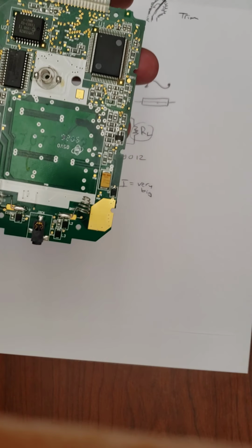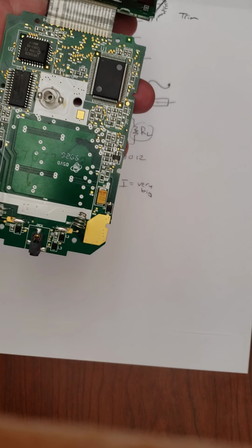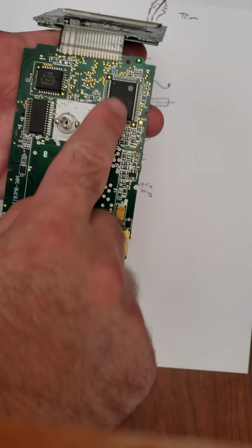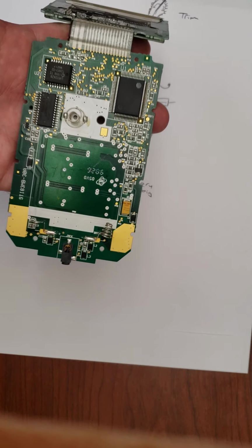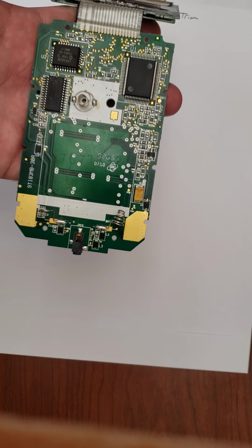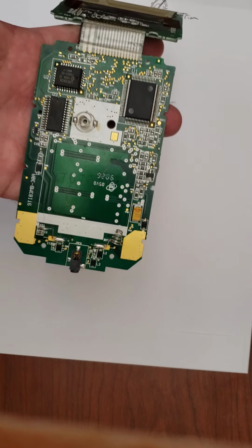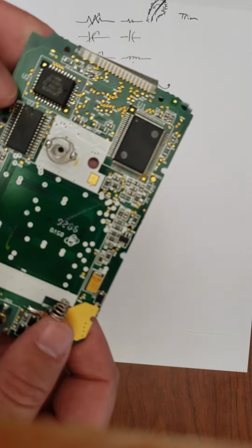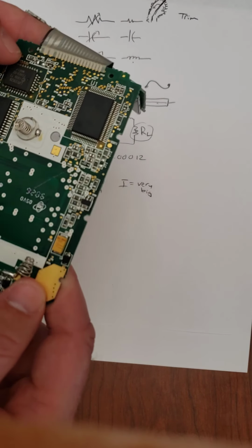Then you take the whole board and blast it with hot air, which is just hot enough to melt all the solder paste. When it melts, that allows the chips and all the little components to settle. Then it goes off and gets cooled, and that's how nobody's sitting here with a soldering iron soldering every single one of these at this really narrow pitch.